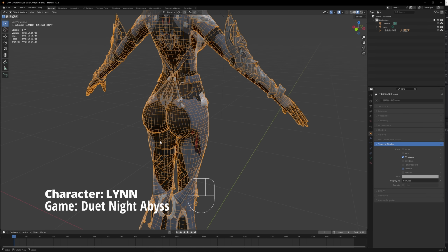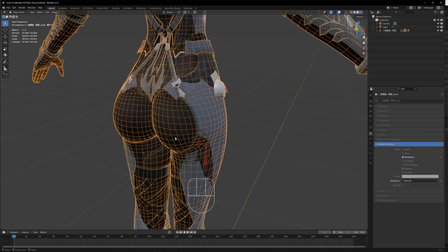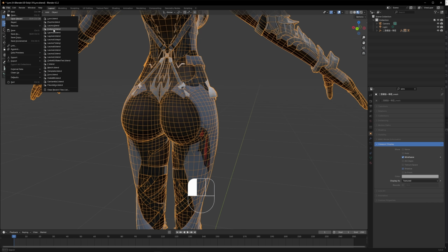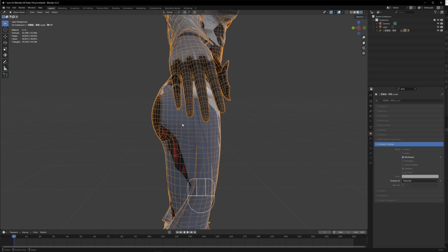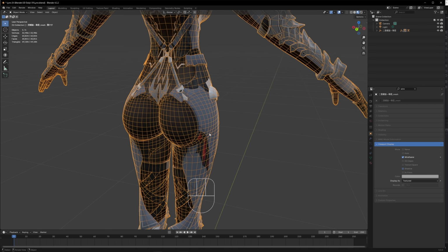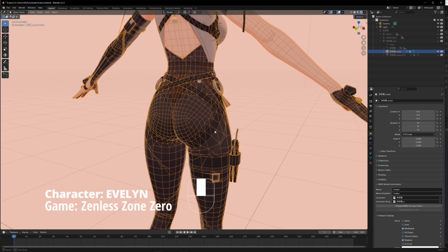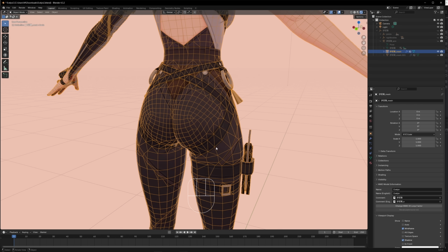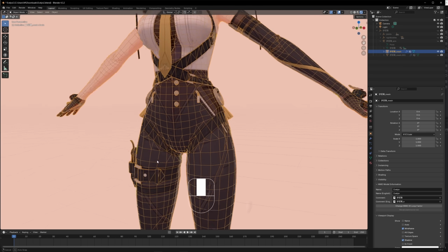butt. This localized density is useful for adding structural support for deformation that is common in those areas, while not blowing up the total polygon count. Actually, a really great example for that would be Evelyn, because for this, right, they just subdivided everything around the butt to make it match the butt's vertices, but here on Evelyn's model, they did something cheeky. They increased the density more locally while keeping the surrounding areas very low budget.